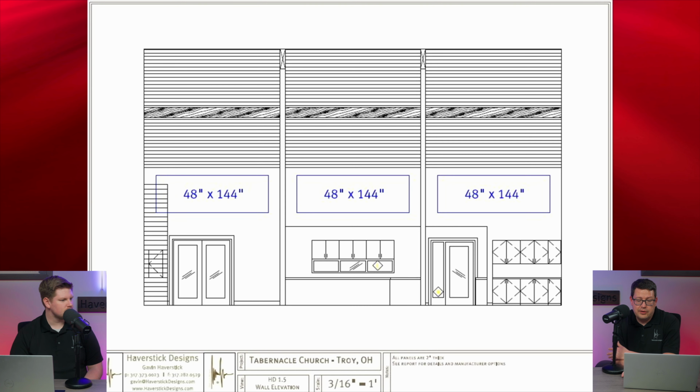And the way that we are able to do that is by doing clouds like this. And these clouds are actually made out of the exact same type of wood that they had the ceiling made out of, except they're hung down from the ceiling and they're wood slats instead of solid pieces of wood all the way along. And these wood slats help to absorb certain frequencies better. And from doing testing, I could tell that there are certain frequency ranges that were more problematic than others. And there's ways that you can do the math and figure out the spacing and the depth of the slat, you can adjust those to tune it for different frequencies, so it's better at absorbing those frequencies.